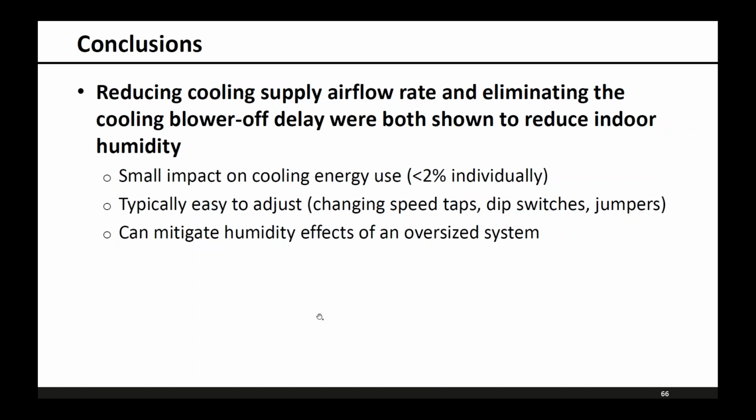And these two items are typically easy to adjust inside the air handler with either motor speed taps, dip switches, or jumpers.